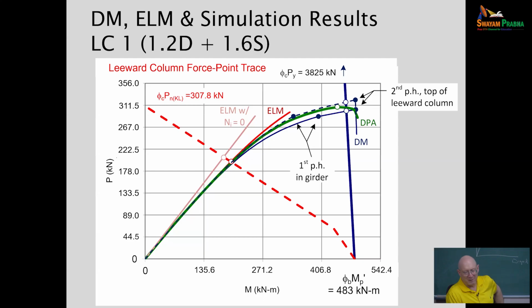In the effective length method, instead we basically are protecting ourselves by saying, okay, if we could take the loads we've got and shift all the loading around, so we've got that same axial load on the column, at what point, if I didn't have any moment, would I fail in axial compression? And so we get an elastic buckling solution for the side sway buckling of the frame.